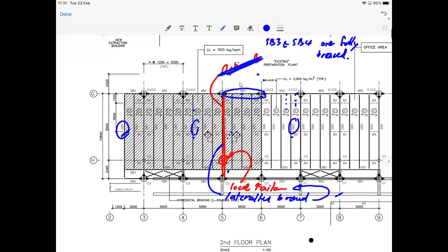Should we write the bending moment diagram of each beam or not? Well, it's up to you, but it would be better if you do, just to show that you have worked this moment, right? Can we use the maximum bending moment? Well, of course, you have to use the maximum moment, wherever it is. Are you going to use a non-maximum moment? When you analyze, your beam is going to fail where the maximum moment occurs. Of course, we need to use the maximum.